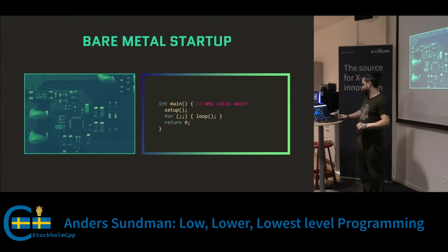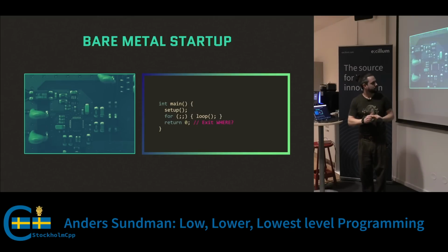All right, so we have a problem here. Who calls main? First problem. Second problem, where do we go from here when we return? Not obvious. We have to go somewhere. The CPU, as long as there are clock cycles on the clock input pin to the CPU, will not stop, ever.